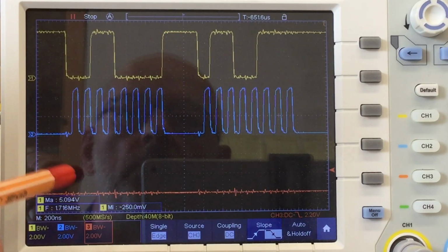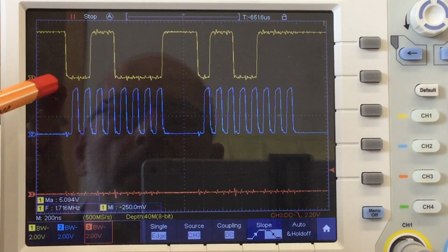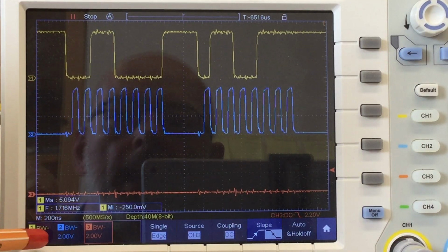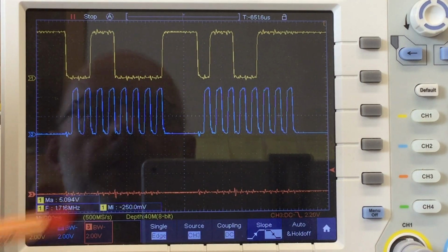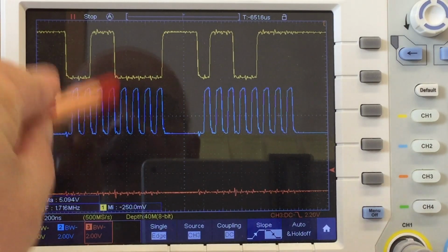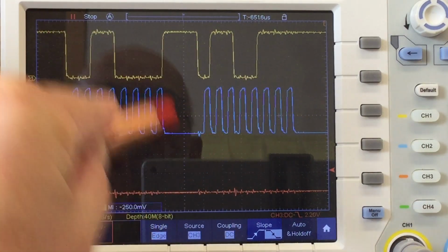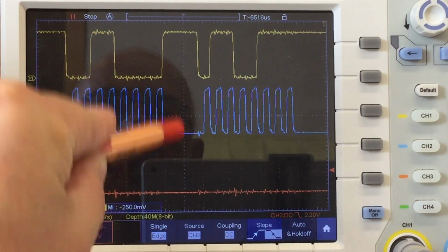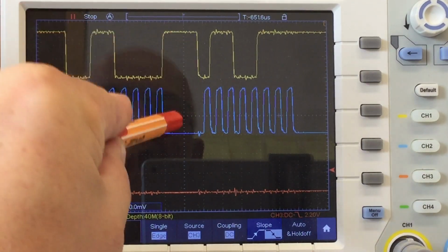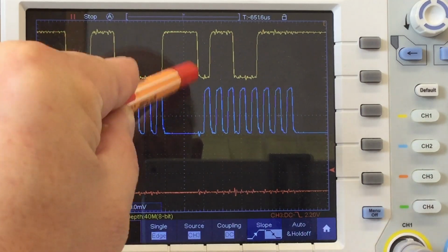If we zoom into one of the 16-bit data packages, and my timescale there is as before 200 nanoseconds, you notice that it still consists of 2 bursts of 8 bits each with a little pause in between. But that little pause is actually the Arduino SPI library.